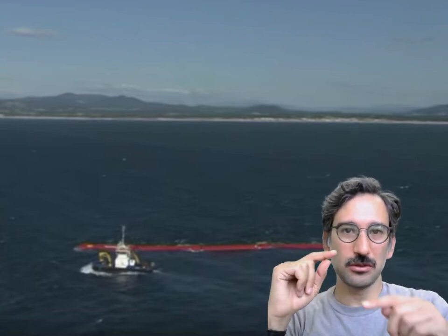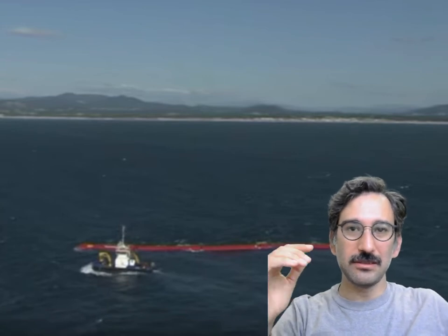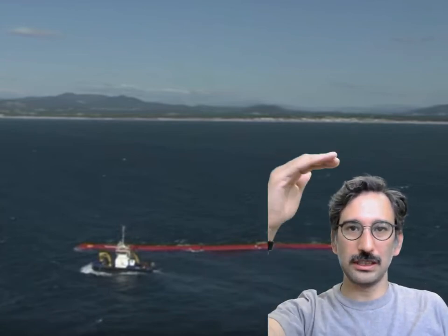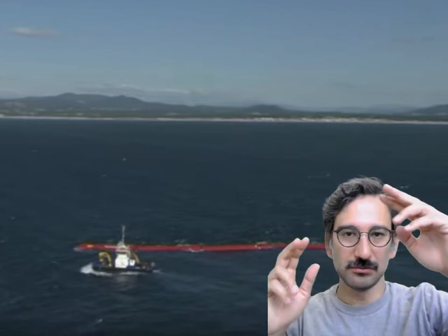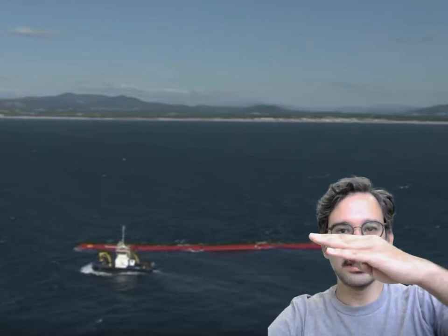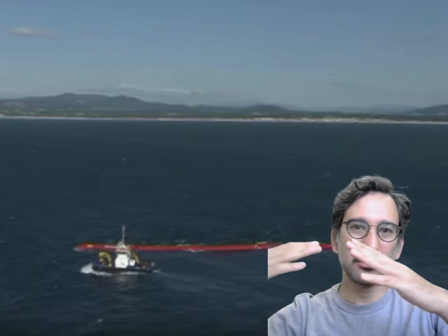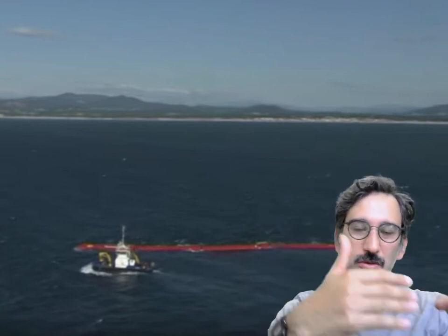But I don't want you to emphasize the electrical system, but look at the mechanical system, because you have sea waves going up and down. That is our V1, and then we have the big snake, the Pelamis device, going up and down. That's another AC movement, sinusoidal movement. That is our V2, and the inductance now is the inertia. So the power transfer from waves to machine will be determined by the phase difference between these two AC systems, right?